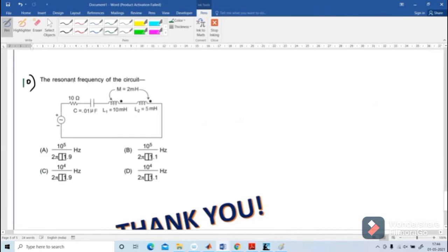Next problem 10. The resonant frequency of the circuit is given. Here I am going to find out the resonant frequency. Resonant frequency F is equal to 1 by 2 pi root LC. There is no single L. Two L's are connected in series with the same connection. There is no opposition here.